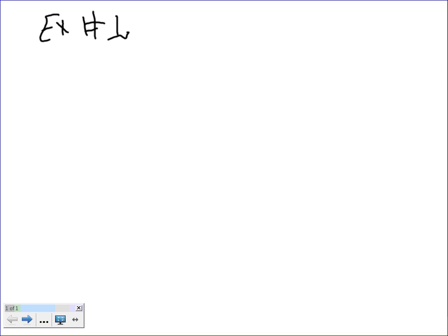Take the air handling unit, Spencer. You take the air handling unit full load current. You do in Excel the size of the overcurrent protection device for it, the size of the feeder, and so forth. Not required by me, but if anybody wants to jump into this project, I will help you as you go through. There's some code related. As you size the branch circuit for the air handling unit, you will tell me exactly where you found the code. All this information is there, guys. We've done it. It's just never been done in an Excel sheet. Adding branch circuits to the Excel sheet. If anybody can jump into this project, I will be able to help you.